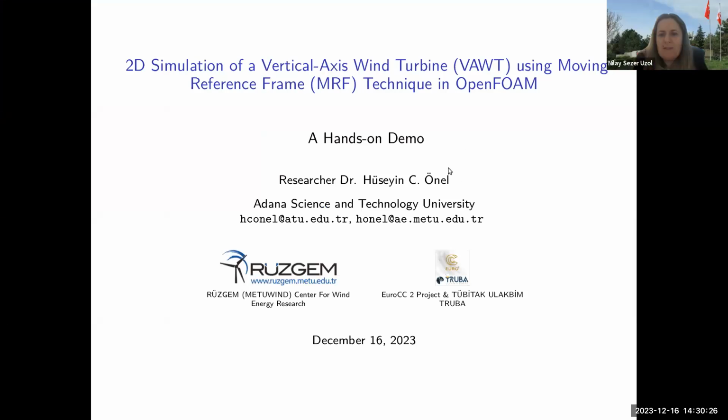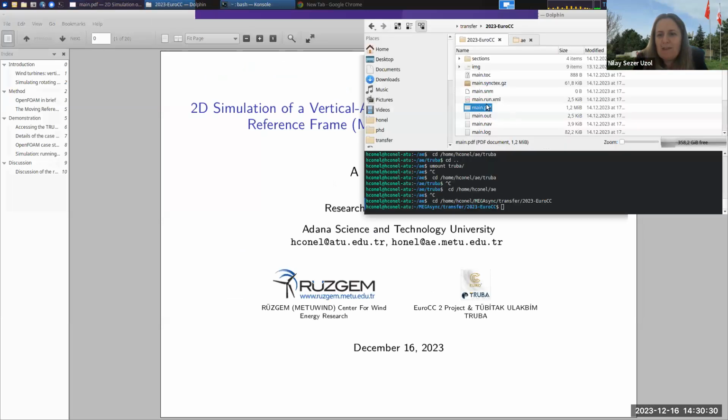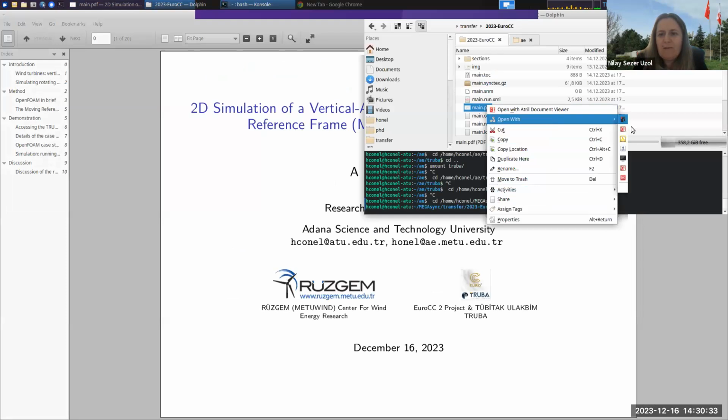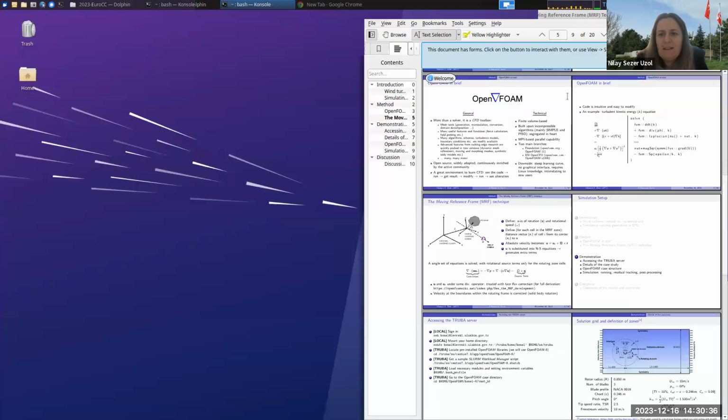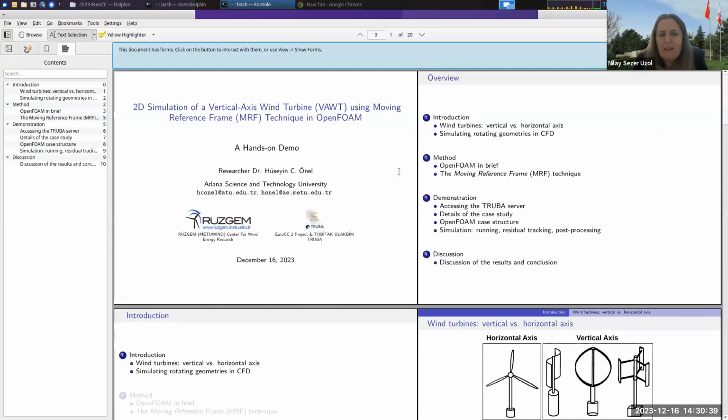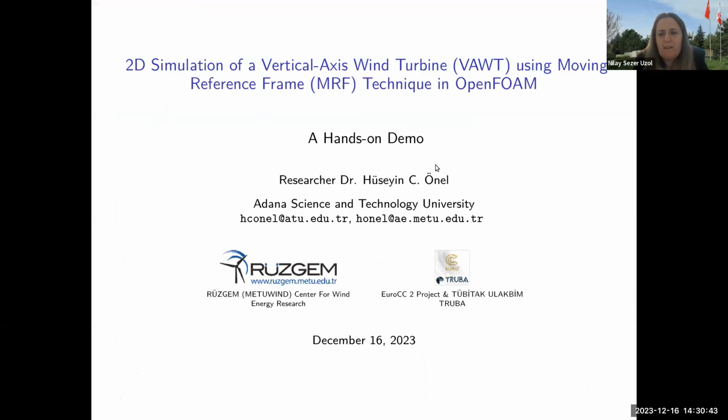Before starting, maybe there was one question about SU2. What is the scalability of SU2 on clusters? I mean, the computation wise. It's a finite volume solver. CFD solvers usually, the scalability depends on the grid size, mesh size, and after some point it goes linear, but then it diverges from the linear scalability as usual. It depends on the problem and the solver methods that you are using. You can easily check the parallel performance yourself as well.